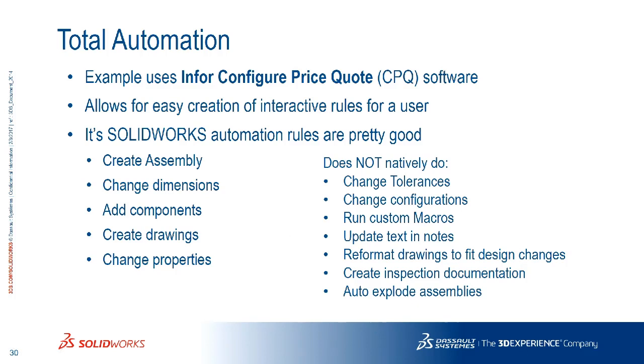Well, here's a little bit more information on that. So yeah, I'm using Infor Configure Price Quote for this. You could use DriveWorks. I think there's a few configurators out on the partner pavilion. It really doesn't matter what you're using because you can extend them beyond just what their capabilities are. So for CPQ, it's pretty good. It creates the assembly, creates the dimensions, adds the components, creates the drawings, and changes some of the properties. But it doesn't change the tolerances. It doesn't change the configurations. It doesn't run custom macros.